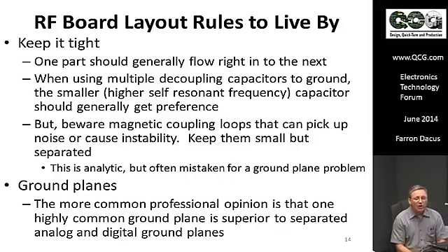Ground planes. Good ground plane methodology is something I have heard argued about my entire career in RF. And among experienced guys, it seems like it runs about 2 to 1 in favor of having one common ground plane. And that is the strategy that I usually adopt myself.